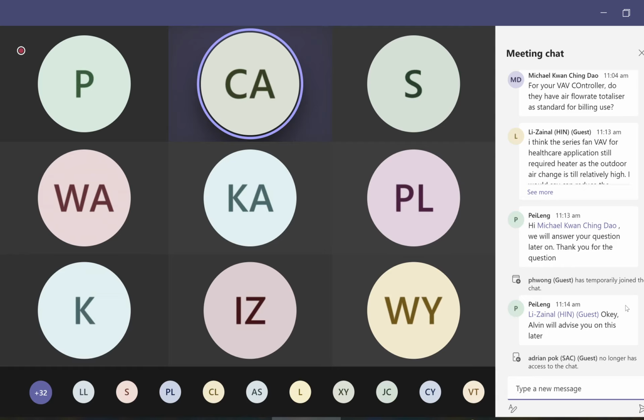The reason why it's so low is because there's just a negligible pressure drop from the averaging sensor and the damper parts. And there's also a static pressure regain. If you look at the box, when the air velocity goes from the inlet into the attenuator section, the air slows down because of the larger cross section. And that's why the pressure drop is relatively low.